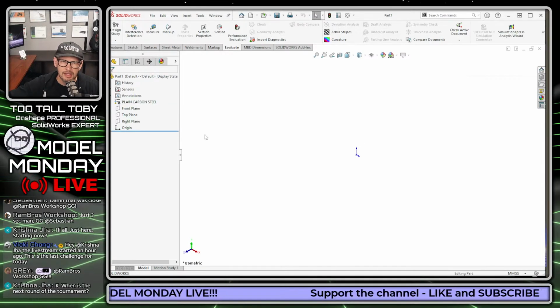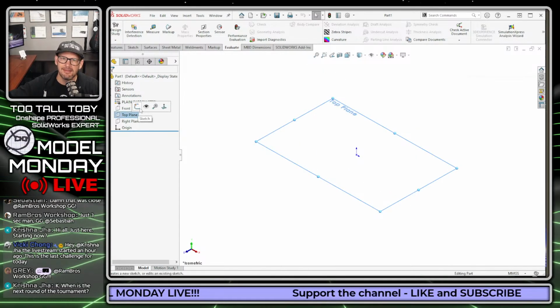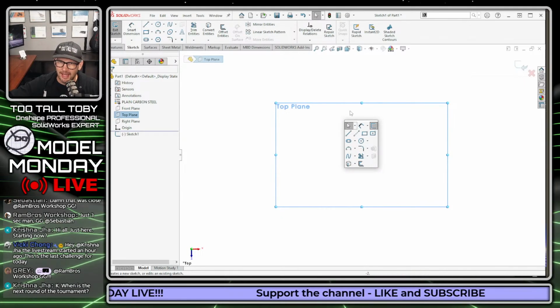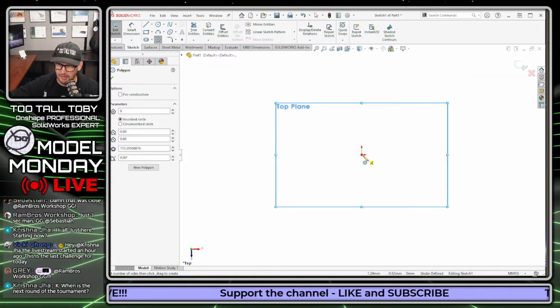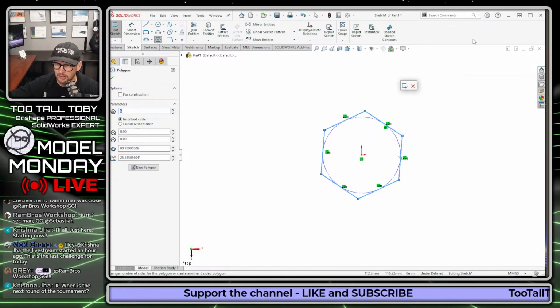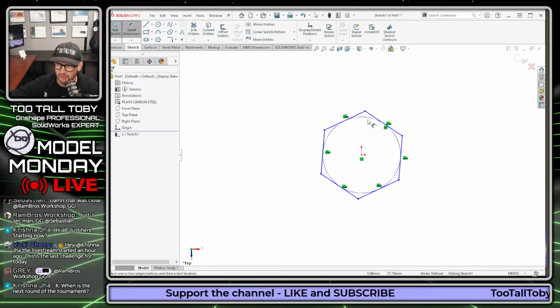And then we can go in here to our top plane, sticking with our game plan, begin a sketch, S key. Looks like actually I don't have hex on my S key menu. So I'm going to go hex, or polygon, click over here, click out here in the background, and then I'll just jump into my smart dimension command, S key smart dimension.